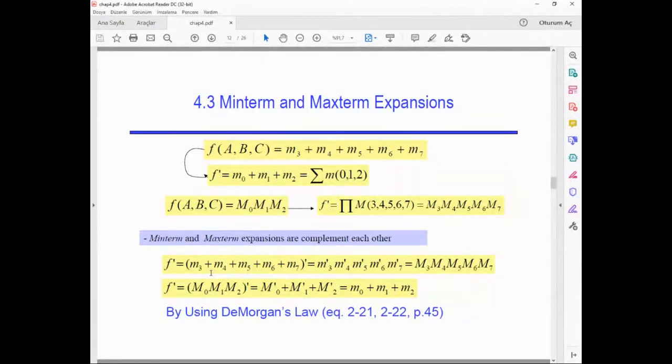So we can say that there is a min term, 3 to 7, they equal 1, and it means min term. So we can complement the min term also. The not F means 0, right? You can complement max terms and min terms. Min term complement is max term. Max term complement is min term.